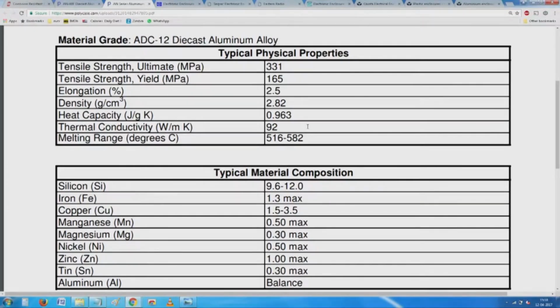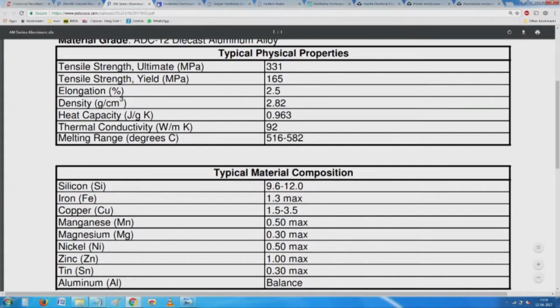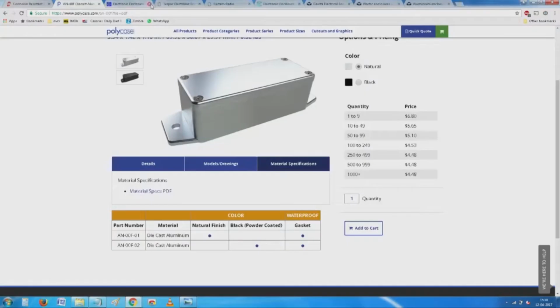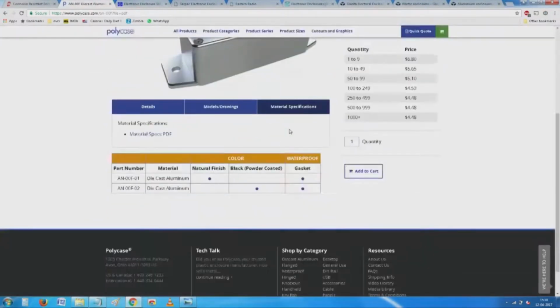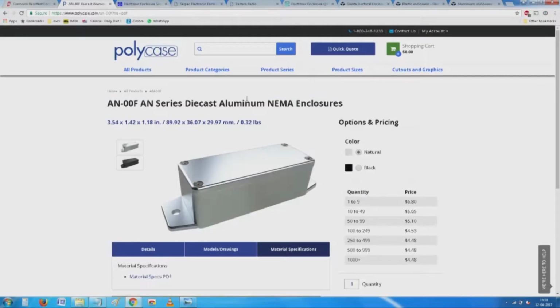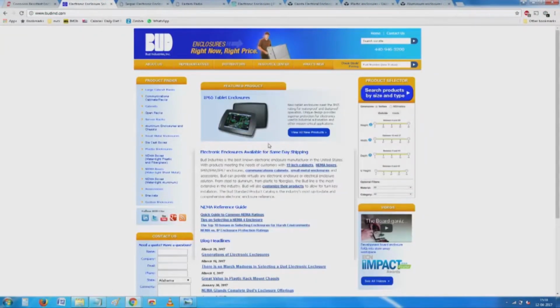So, here basically it looks like this is an aluminum case, but has traces of silicon, and a large amount of silicon composition. So, it is an aluminum silicon case which will make this very suitable for our application. It is not for us to copy or anything, it is for us to understand how it is. So, as we go on,